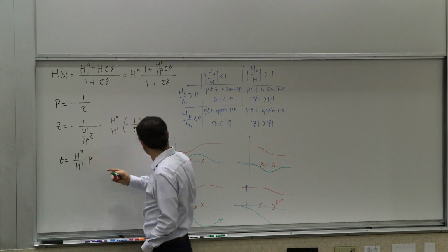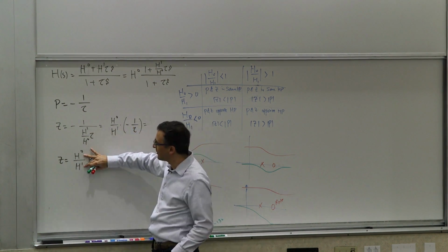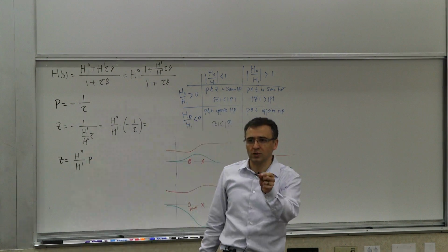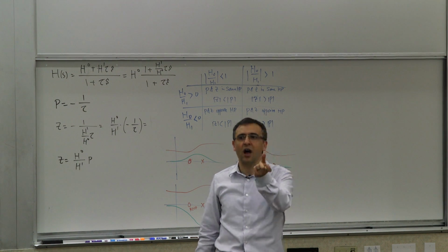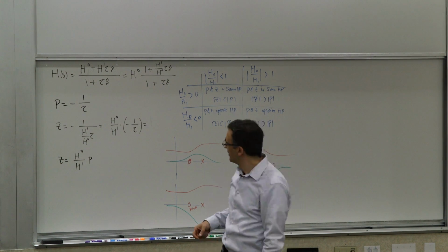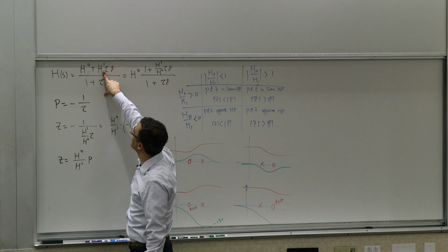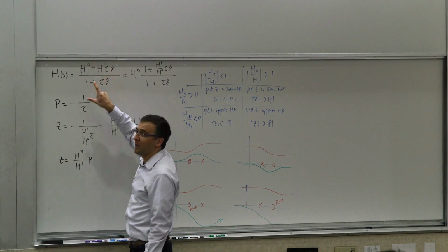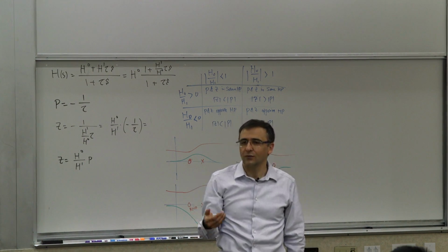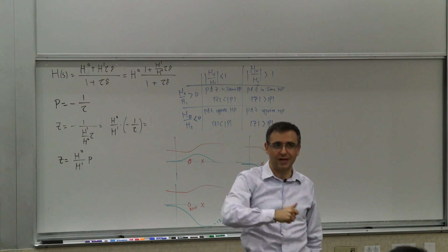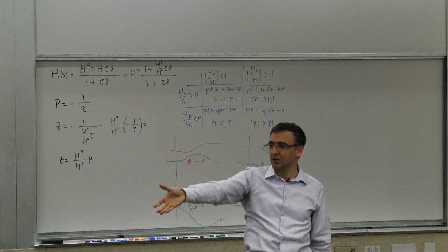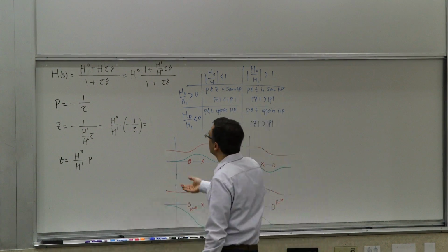Now, what do you mean by being able to easily tell? Because if you're caring about left half and right half plane, you don't even need to calculate these things. For example, if you're dealing with a capacitor, you short circuit it and open circuit it, and you look at the sign of H0. That's one of the metrics. For you to have a zero to begin with, you have to have a capacitor that when you short circuit, it produces a non-zero transfer constant. So if you see a capacitor that you short circuit and your transfer constant is non-zero, or a capacitor that you open circuit and your transfer constant is zero, that means you have a zero.